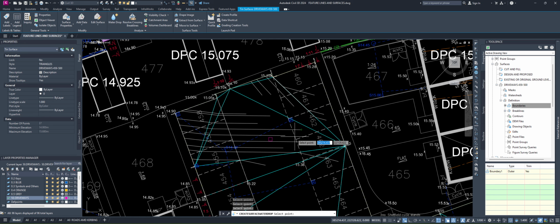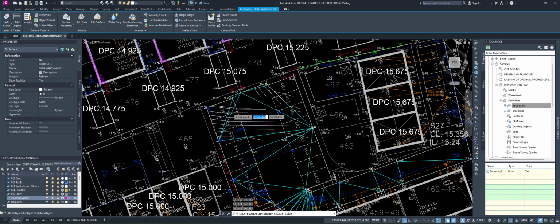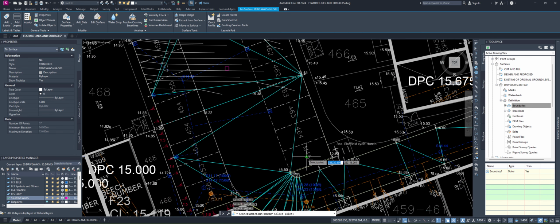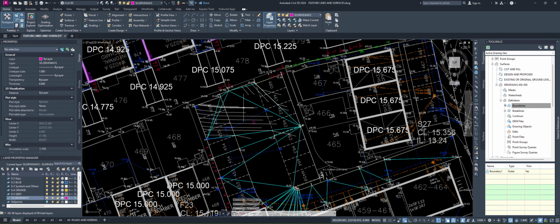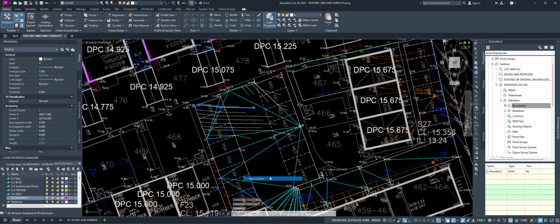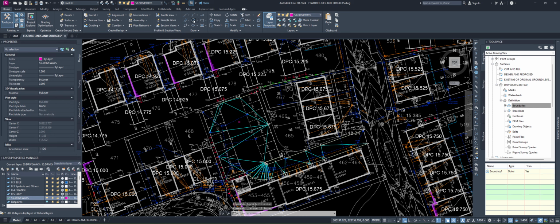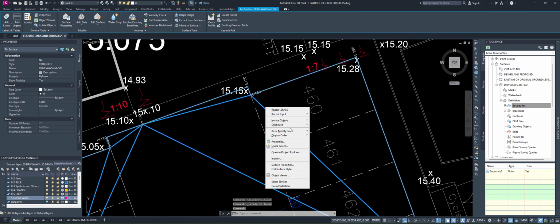The water drop doesn't exactly work the way I imagined it would, because it follows the triangles. If we have a line here and here, instructing the triangles to connect with that line, I can actually show you. Let me delete all the water drops and let me draw a line. I'm going to hide that surface just for the moment.